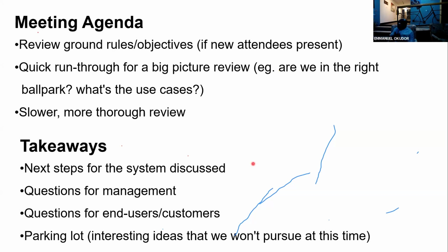So, 2 out of 3. Now, when you talk about 2 out of 3, it means they are going to have 3 transmitters as against 1. The 3 transmitters are more efficient and more reliable in terms of voting architecture philosophy.